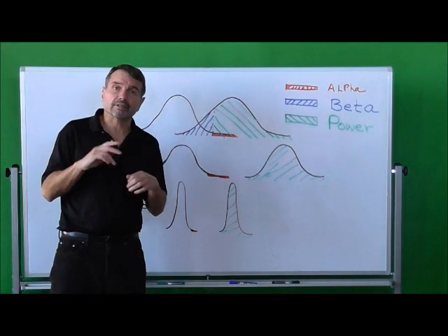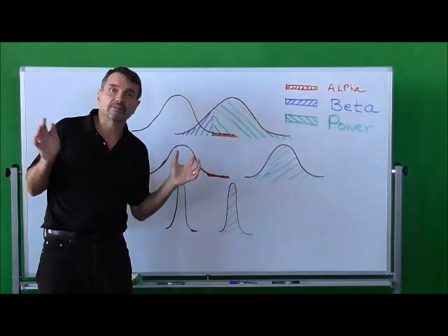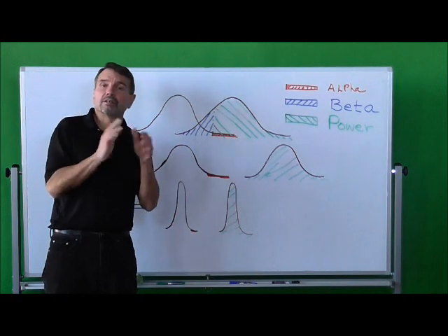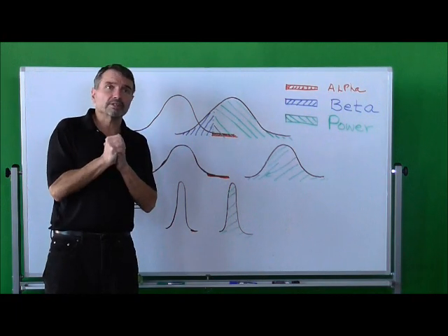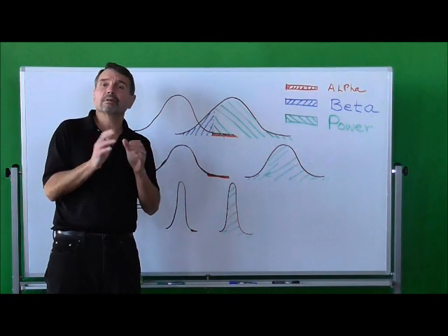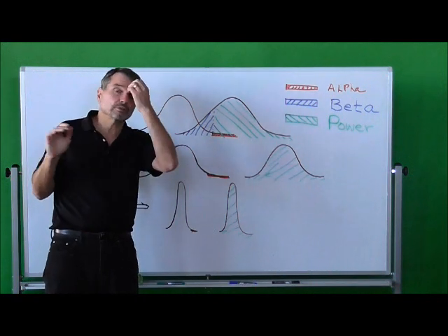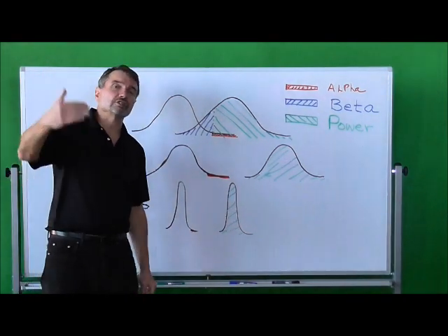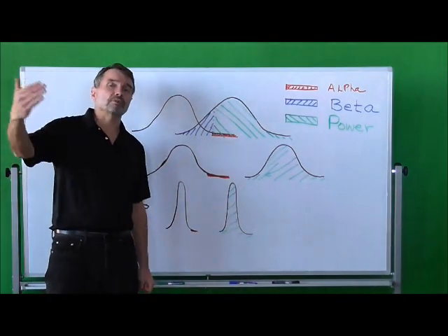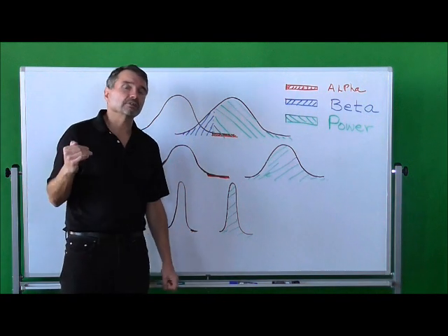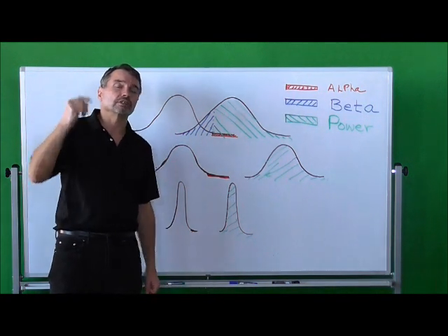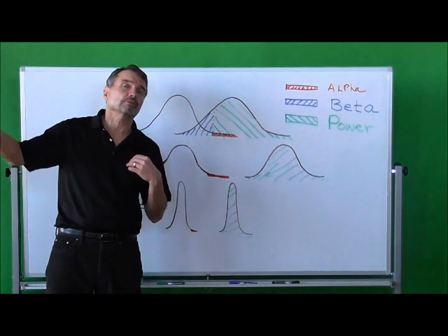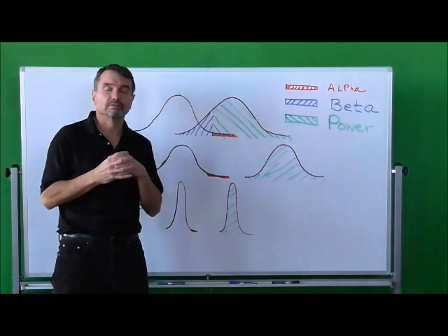Environment might be the other factor that is a cause of variability. If that's the case, then do it in the quickest period possible, maybe in the morning or maybe in the afternoon, but you don't want to do it over 2 to 3 days. There may be multiple different machines that you would be running the experimental process over. And if that's the case, then just pick one machine and don't do it with the inherent variation that's going to come from doing it across multiple different machines.